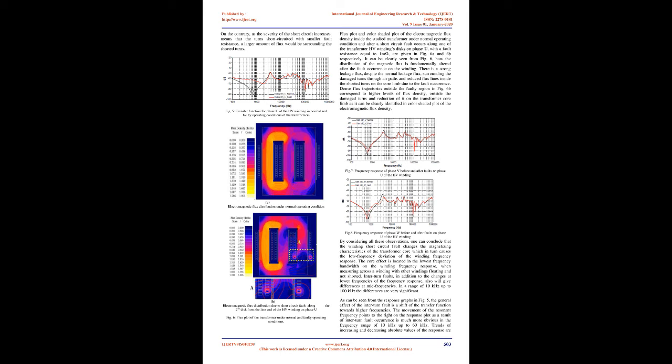Also, the values above zero for the spectrum deviation and below unity for the correlation coefficient in the 1-10 kHz and 10-100 kHz frequency bands indicate the differences between the faulted and non-faulted responses at medium frequencies. From the table, the indicators illustrate good agreement between the responses from 100 kHz up to 1 MHz, which proves that the high frequencies are not affected by the interturn fault.